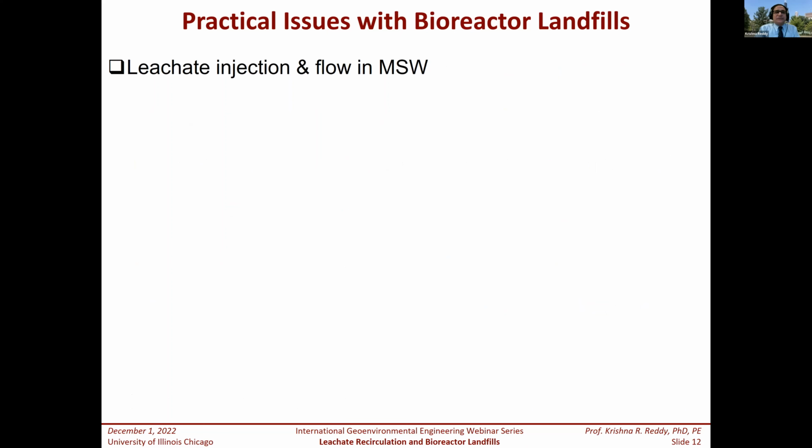So everybody wants to do this one, right? As I said, landfill owners really love this one because they are saving the cost for leachate recirculation, leachate treatment. But there are a lot of practical issues in dealing with these bioreactor landfills. The first thing is leachate injection and flow in the municipal solid waste.